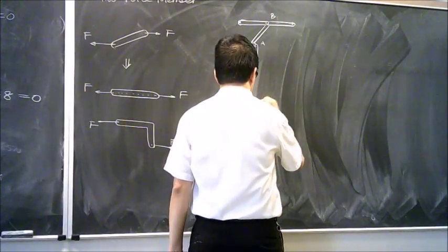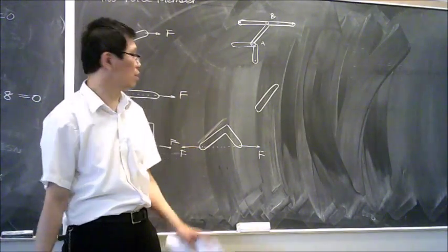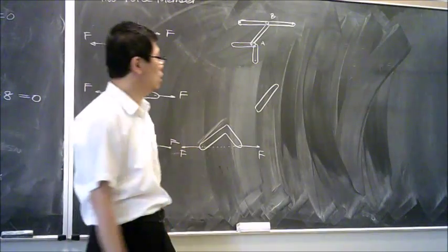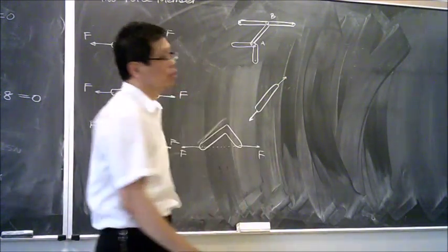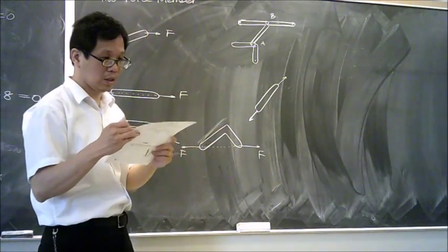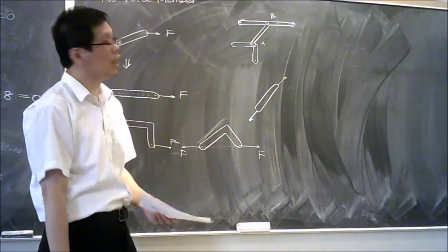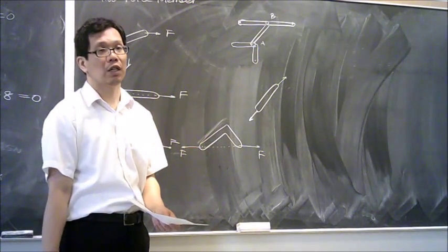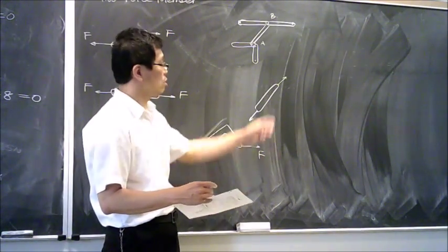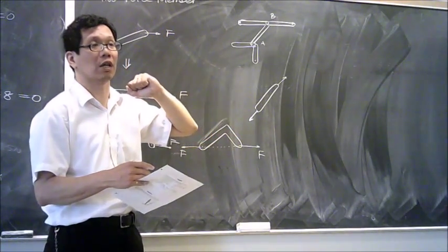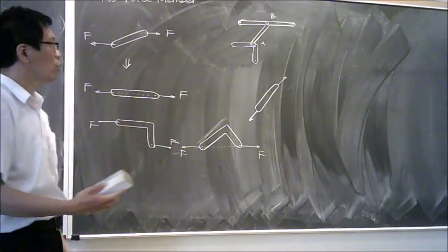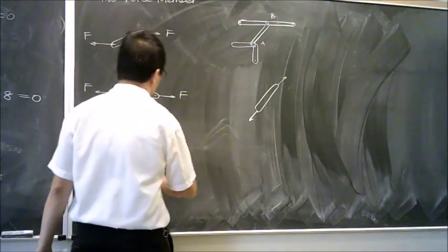So with that information, this is the two force member. When it's a two force member, the orientation is going to be aligned to how the force has been applied to it. So in this case, we actually know the direction of forces applied at A and at B. That's the physical configuration of a two force member. In other words, if you know it's a two force member and I give you the direction of the object, it also implies you know the direction of the forces at both ends. Does that make sense to everybody? Two force members are common in chapter 6 when we're talking about structures. Two force members are actually everywhere, so that is something I would like you to know beforehand.